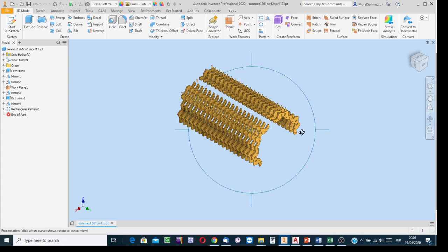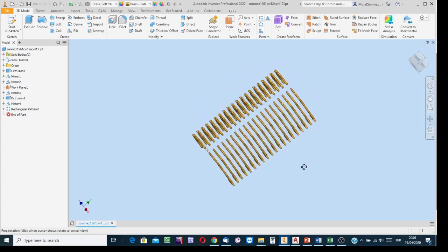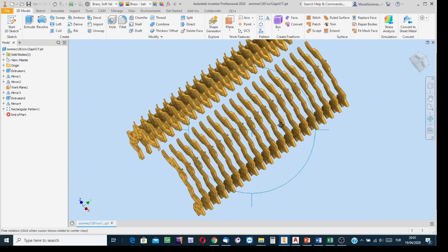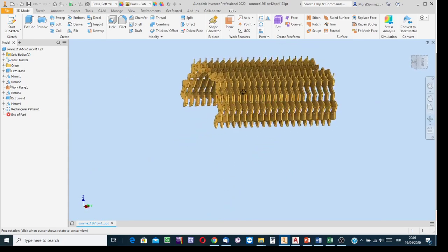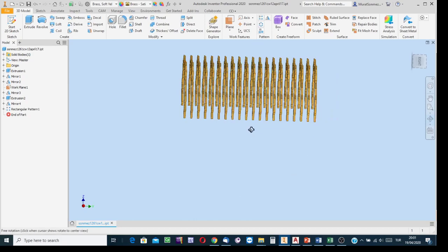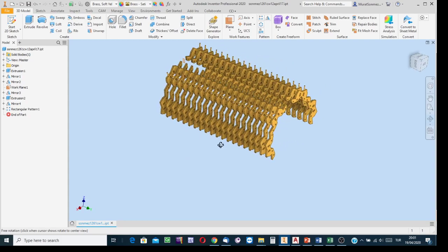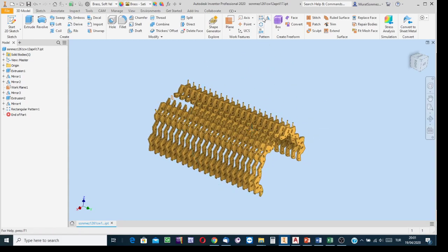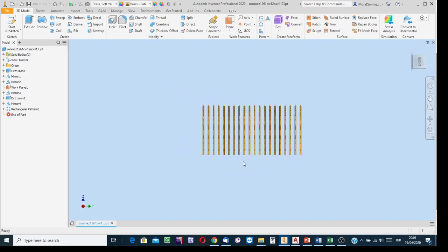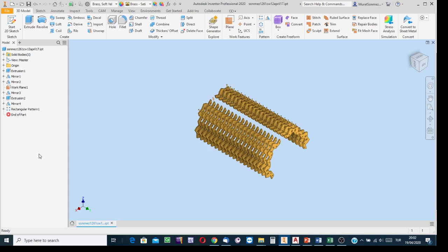You see, in one direction I managed to create identical copies using this tool. Okay, a rectangular pattern, but you see, if you say, hocam, it is not a rectangle, in this direction there is a row. There might be more rows. Then edit it. Since I created this array in one direction, there is only one column, or say one row.